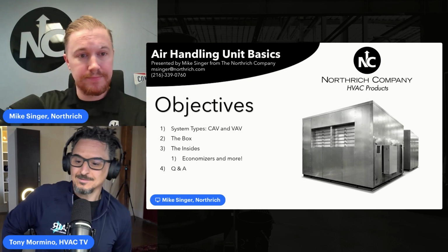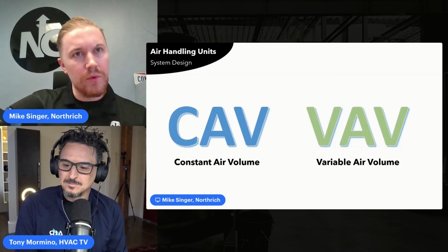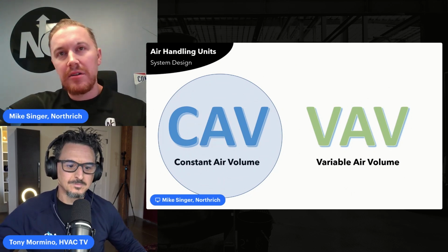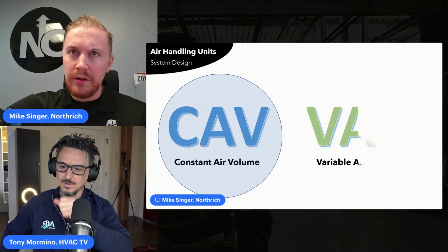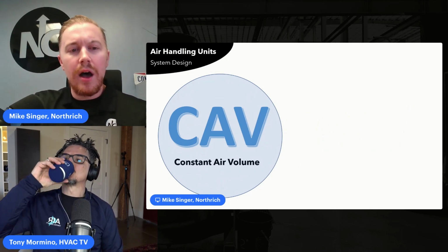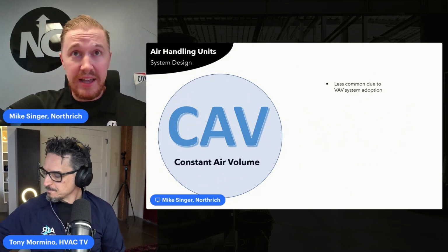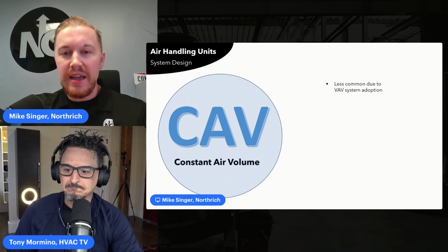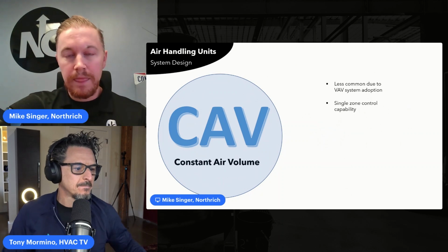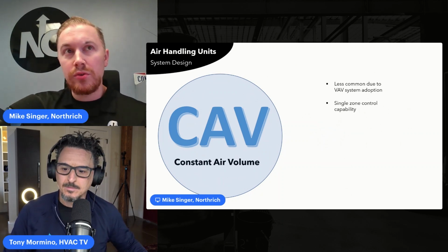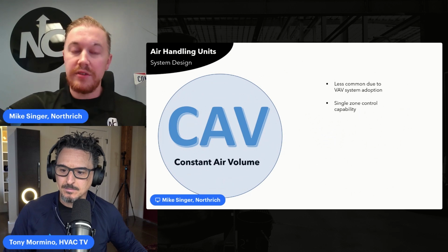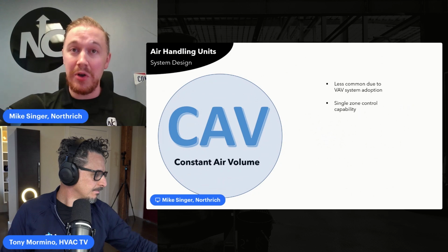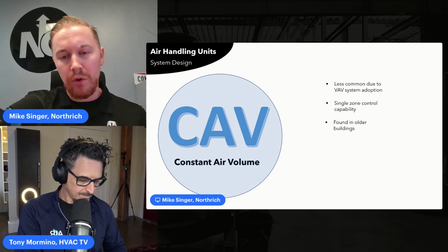Yeah, for sure. Okay. So we've got constant air volume systems, CAV, and we have variable air volume systems. Let's first take a look at some of the generalities of constant air volume systems. In today's world, they're going to be less common, way less common, due to the adoption of VAV systems over the past few decades. They're going to provide single zone control capability. So I have one air handling unit that's constant volume. I have one thermostat, one zone. We'll get more into that as we roll forward.